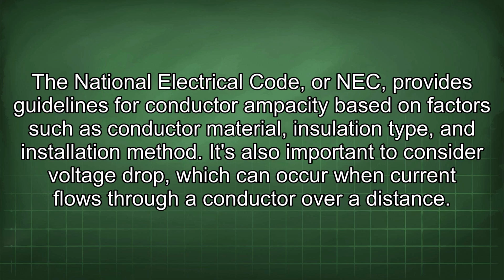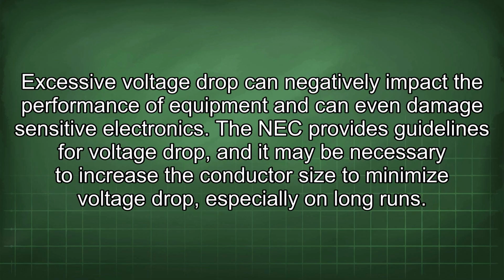and installation method. It's also important to consider voltage drop, which can occur when current flows through a conductor over a distance. Excessive voltage drop can negatively impact the performance of equipment and can even damage sensitive electronics. The NEC provides guidelines for voltage drop, and it may be necessary to increase the conductor size to minimize voltage drop, especially on long runs.